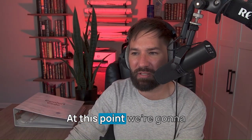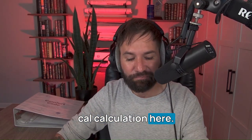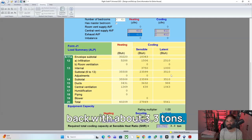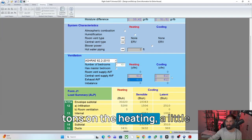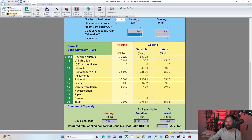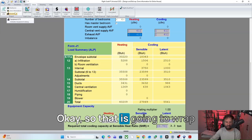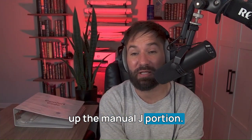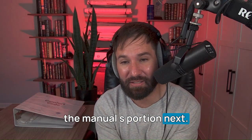At this point, we're going to look at our total load calculation here, and it looks like we came back with about 3.3 tons. It's actually 3.3 tons on the heating, a little bit less on the cooling. And that's really it. There's not too much else. Okay, so that is going to wrap up the Manual J portion. And we are going to move into the Manual S portion next.